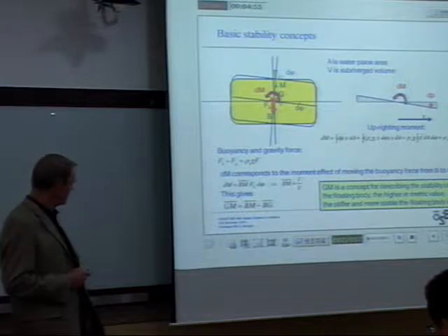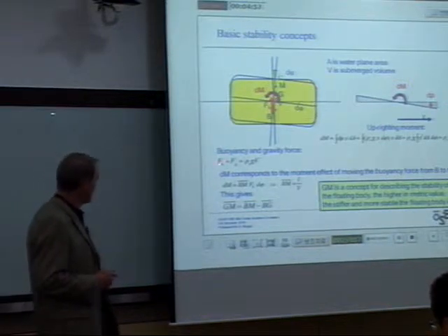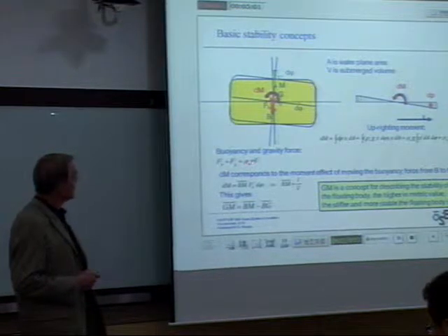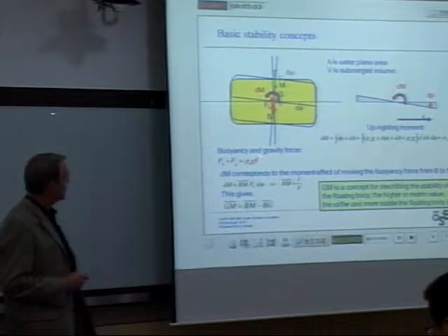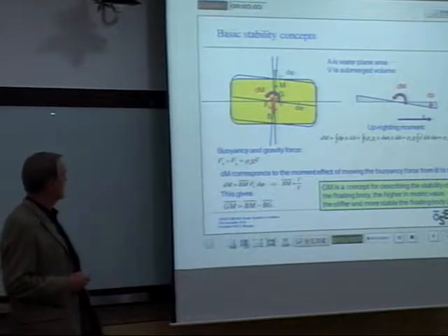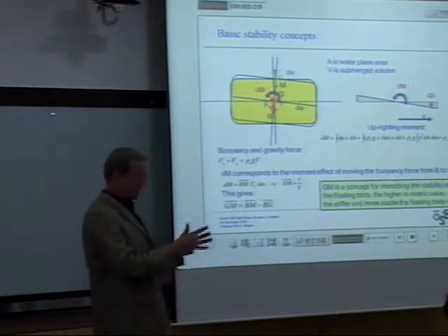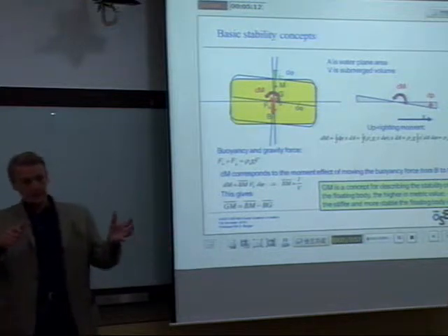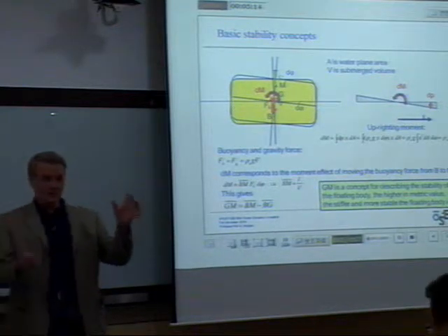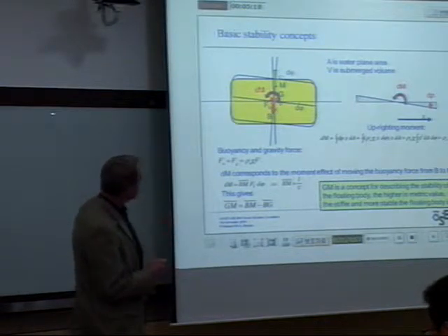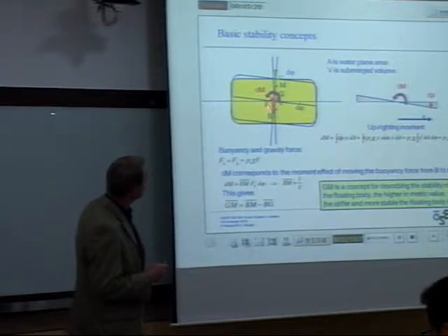And of course, you have the buoyancy force equal to the gravity force, which is the density of water, acceleration of gravity, and the displaced volume. And then we can say that the fact that we're getting this correction moment corresponds to moving the buoyancy force.